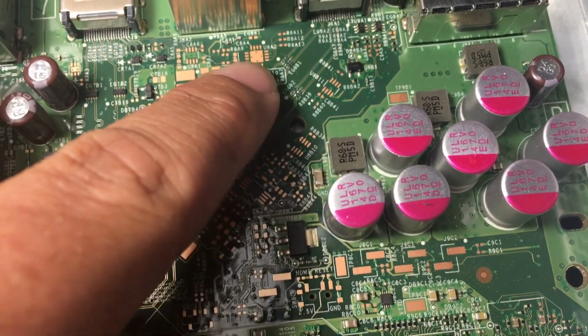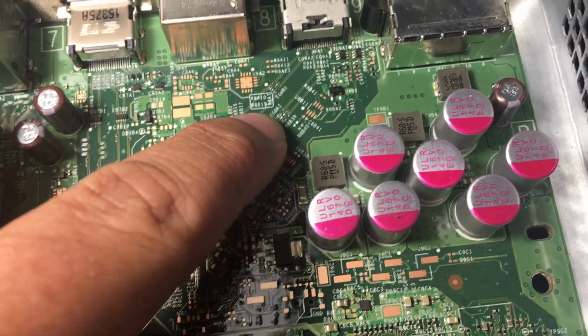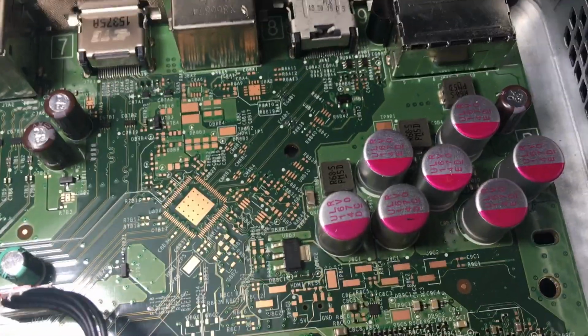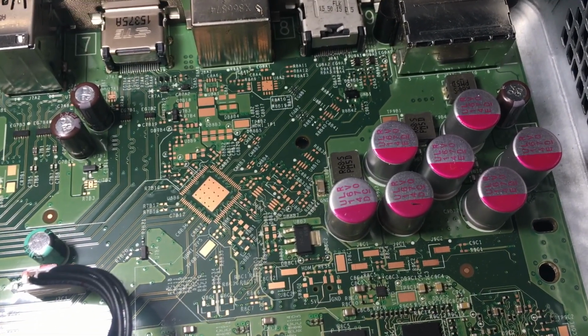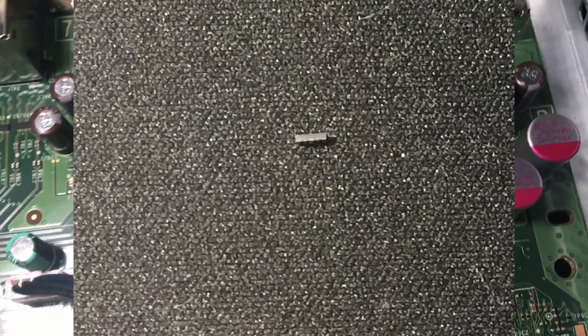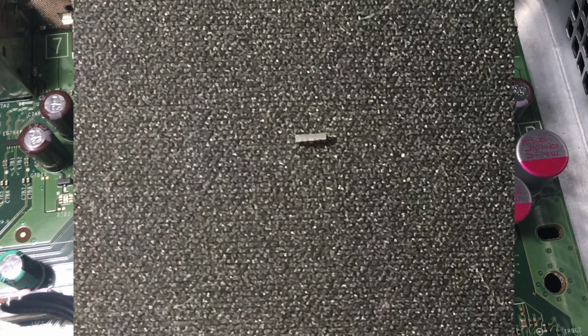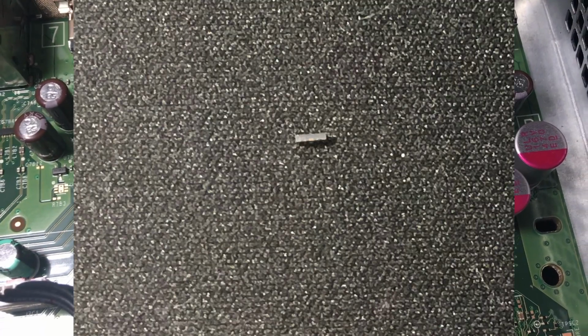So you'll see in a little bit those two filters on. Basically, I'm going to drop them down, and I'm going to show you again pictures of those particular filters. They have soldering points on the outside edge and also on the bottom. So if you apply a little heat to the edge, it'll solder down okay. It's a little bit tricky because they're really tiny, so I'm going to need my magnifying glass when I'm